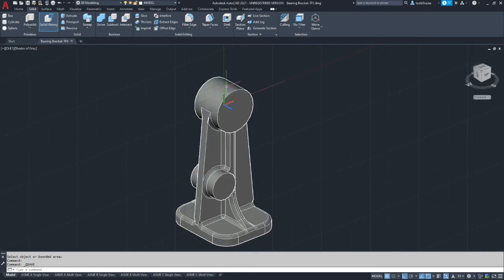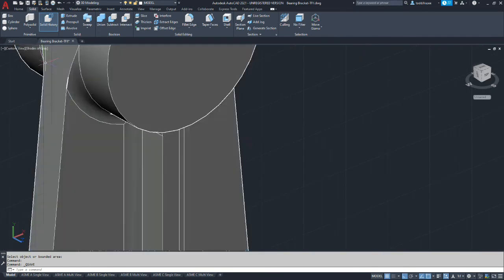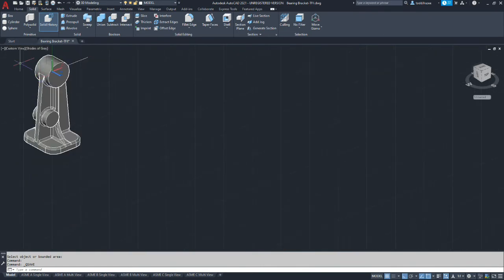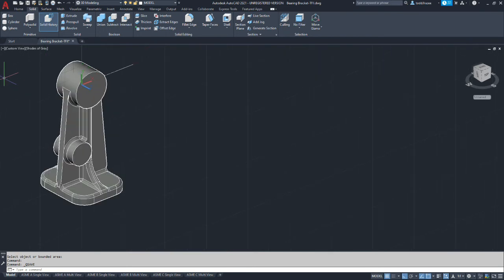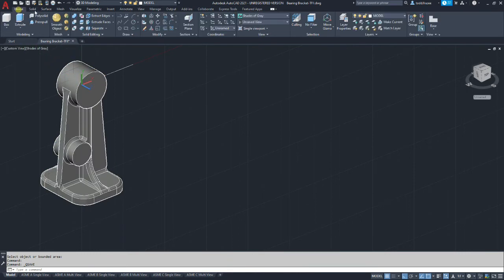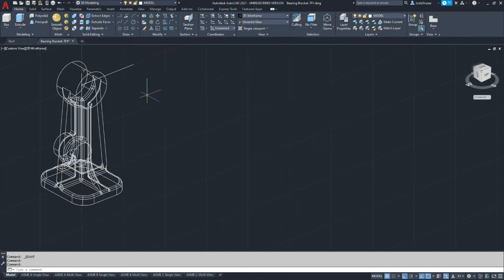Besides attempting to put the fillet on the top of the part. Let's go to wireframe. There's always other methods to do this, but the method I'm going to use is to actually draw the circle in the center on the origin, shoot it straight up to the height that needs to be. So we are going to go to wireframe mode for that.